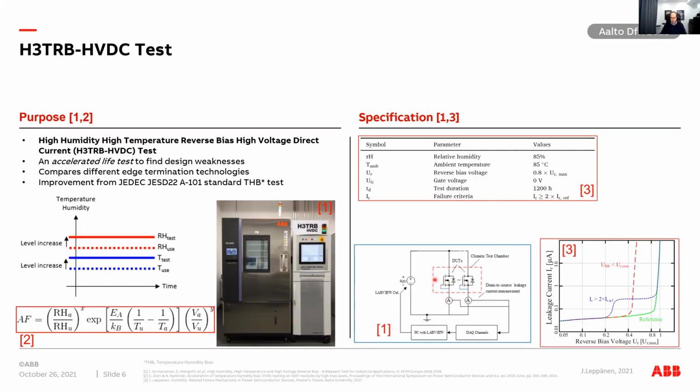And the test setup schematically looks like this, that we have these DUTs there. These are actually MOSFETs now, and there can be plenty of them. And then we have current monitoring for each, and then we have this kind of data acquisition measurement. And in the LabVIEW software, we monitor this data, and when we have an exceedance of this limit, we cut each of these channels separately nowadays.